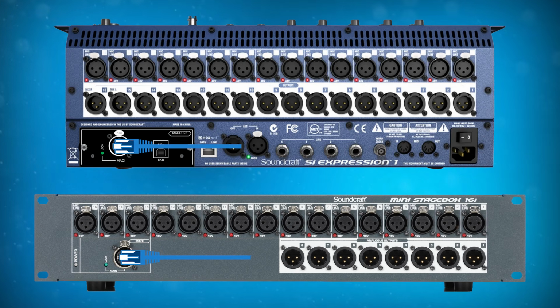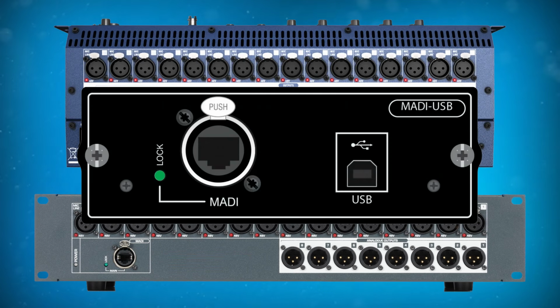The lock lights on the MADI card should both be lit solid. If these lights are flashing, try a different cable. The optimal cable type is Cat5 unshielded under 100 meters or about 300 feet. Although other types of Ethernet variants can work, we recommend trying with the shortest available Cat5 unshielded that you can find if you're experiencing issues.